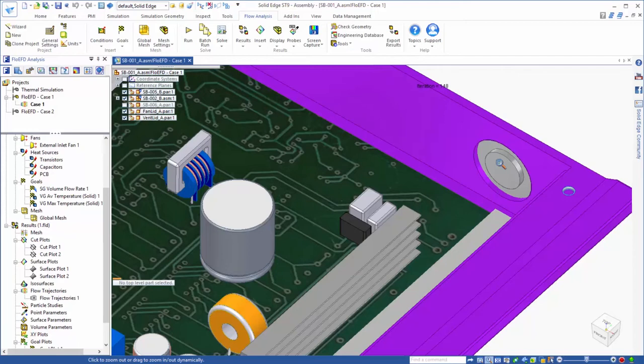One of the ideas that we would like to test based on our first solution is to shift the fan slightly towards the center of the amp. We are hoping to divert a portion of the incoming airflow more towards the central region of the board while still maintaining strong flow through the heatsink. Additionally, we'll go ahead and increase the length of the heatsink fins to further help cool the transistors.